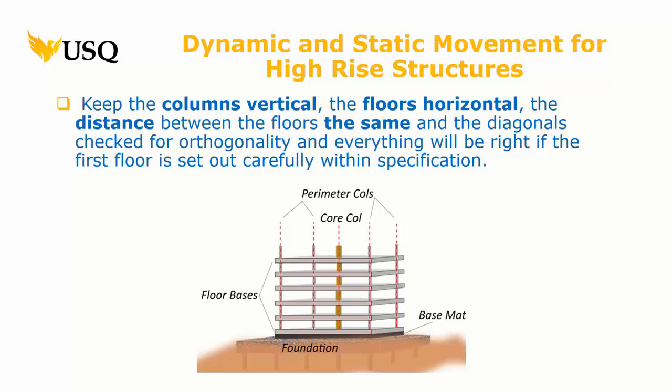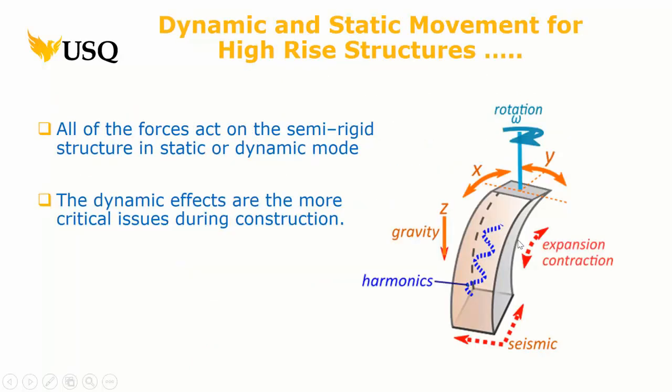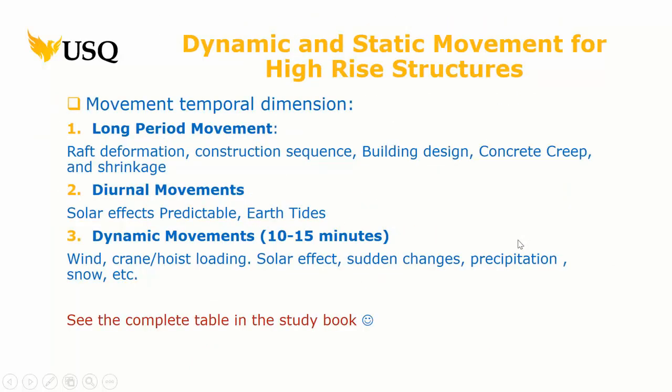In some cases, these rafts are actually floating because you can't get it deep enough to actually go to, say, bedrock or whatever, right? Well, they'll make the raft float on purpose, and then you have to monitor what the movement would be. They're very large and big buildings, massive, and a huge amount of concrete, obviously. So that's the long-term effect.